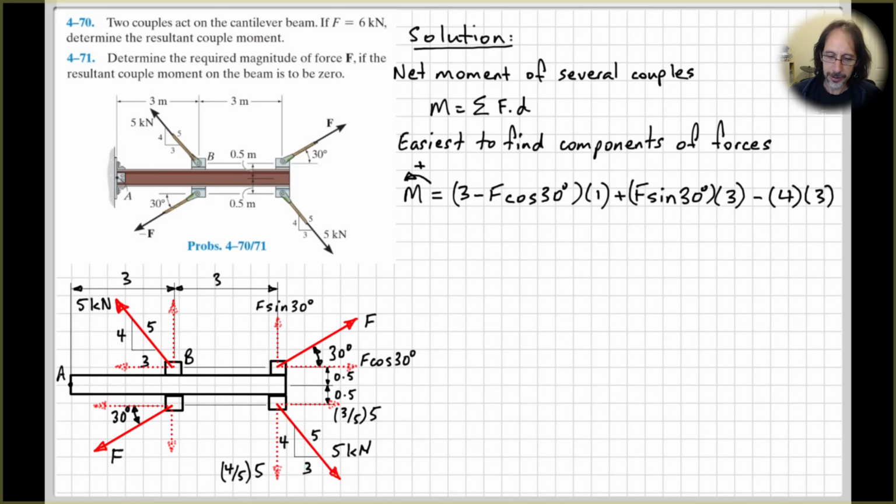So hopefully you can see that will tend to rotate around like that. So that'll be in the clockwise direction. Note that up here, we didn't indicate where we're taking moments about. Okay, so because this is a problem that we know that everything is a couple, we know that we can just do force times the distance between the two forces that make up the couple.